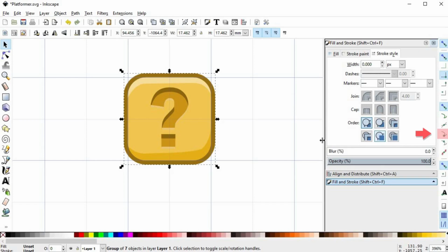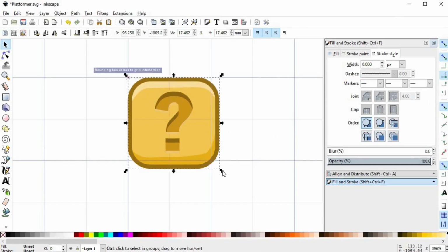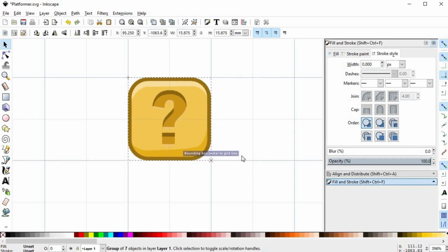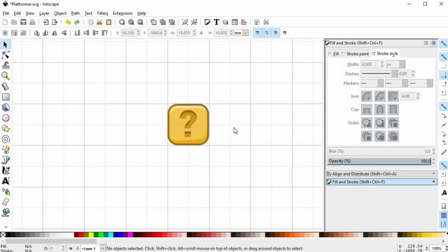This will force snapping to nodes instead of bounding boxes, and it takes precedence over any other option, so you have to disable it temporarily. Now you should be able to make it snap to a corner, and using the opposite arrow, you can scale it in. As soon as you scale, it's gonna snap and fit perfectly inside the grid rectangle. Now don't forget to turn snapping to nodes back on, because it's really important for other types of snapping. Well, finally we are done with the block.